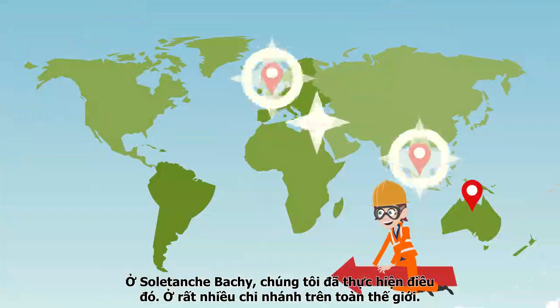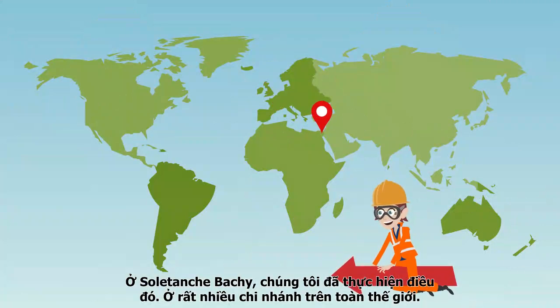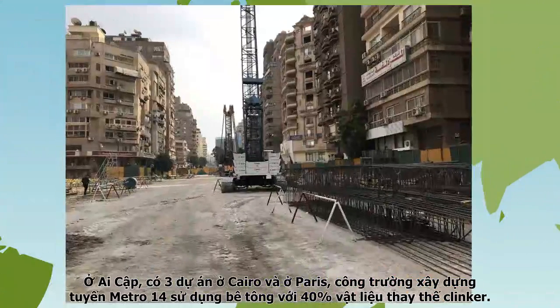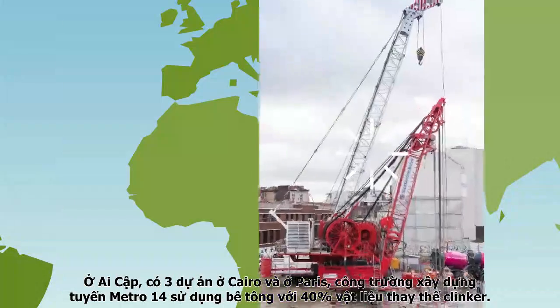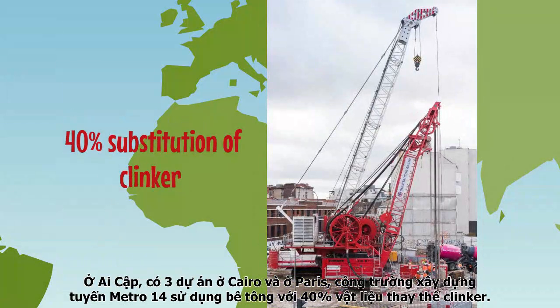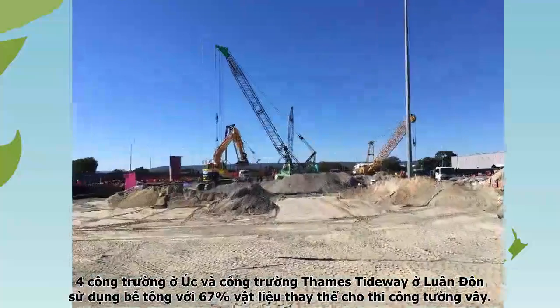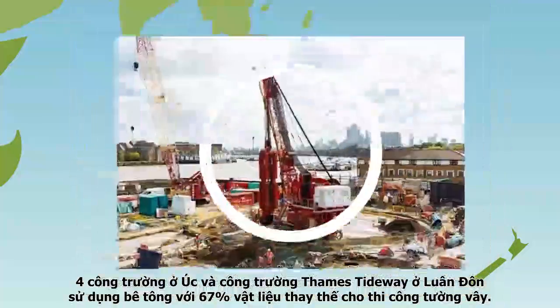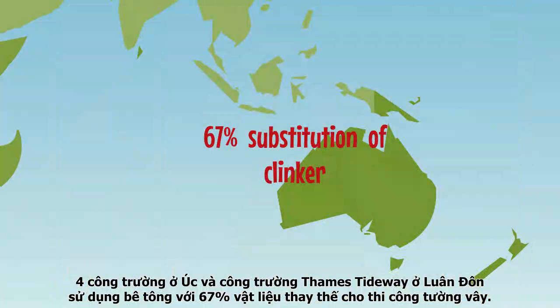And at Soletanche-Bachy, we already do it on a large number of construction sites all over the world. In Egypt, the Cairo Line 3 project and construction sites in Paris Metro Line 14 used a concrete with 40% substitution of clinker. The Forcefield site in Australia and the Thames Tideway site in London used concrete with 67% clinker substitution to produce diaphragm walls.